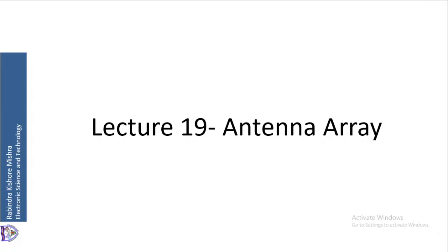Now, as we know, the power that is radiated by antenna will decrease as 1 by r in the far field. So as you keep on increasing the distance, the amount of power received will decrease, which means we cannot cover a large distance if we use a single antenna.